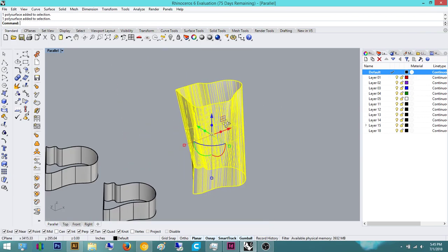So you can actually type in the command called cap. Now this will create the top and the bottom portion for you. It's like a shortcut, so you don't have to do any random extrusions. You don't have to make it more complicated than it has to be. So you type in CAP, and you hit enter, and it will say created 2 caps resulted in one closed polysurface. Now this is a very important part. If you look at where I'm highlighting closed, that is extremely important. I'm going to keep mentioning this because this is so important.